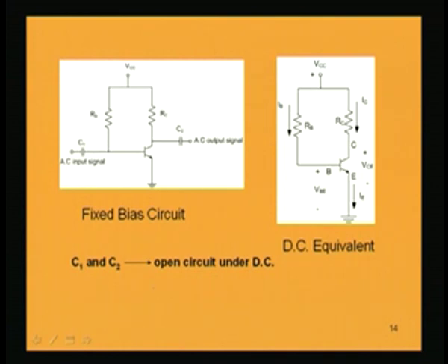If we consider the reactance of the capacitor, 1 by 2 pi f c is the reactance. Now, frequency for this DC circuit is 0. So, if f is 0, then the whole capacitive reactance offered by this capacitance is infinite. When this capacitance is offering infinite reactance, there cannot be any current flow, that means it is equivalent to open circuiting this part and this part.